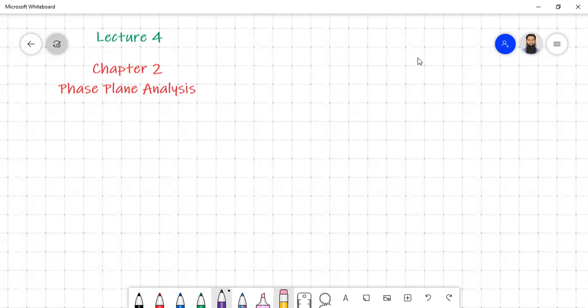Now here, just consider a nonlinear system, that is a pendulum, a freewheeling pendulum. So we'll try to figure out the corresponding transfer function of the pendulum, and then we'll find out its corresponding state space representation, then the steps that we have followed: the equilibrium point, eigenvalue, eigenvector, then finally going for the phase portrait.